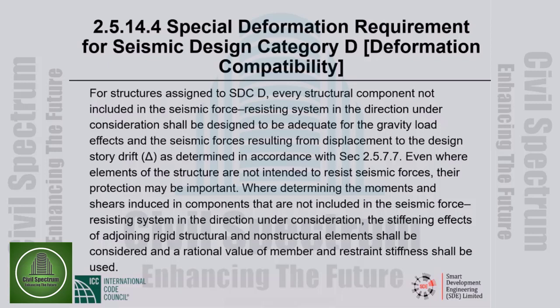Instead of reading, I will repeat what I said yesterday. Let's take a building frame system, as we called it. The shear walls carry all the lateral loads. The frames carry all the gravity. Lateral resistance is separated from gravity resistance.